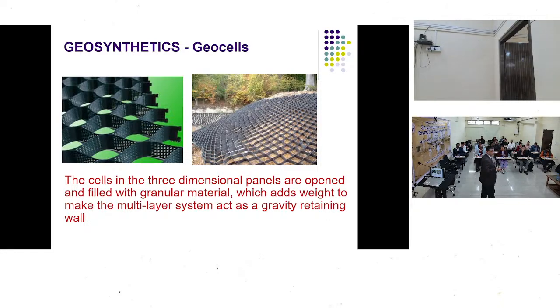These are three-dimensional open spaces. Basically, you have matrices of it, and in these geocells you can fill in granular material. Now, these geocells are confining that granular material by their design, and so they are able to take loads equivalent to the crushing strength.